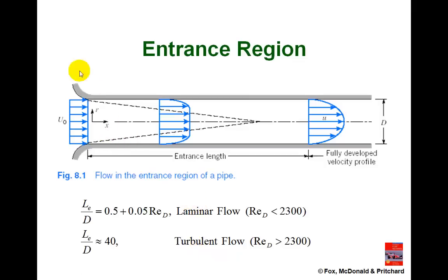If flow starts up from a reservoir over here on the left side and enters a pipe, especially with a smooth entrance as shown here, the flow is characterized by an almost blunt profile at a constant velocity. This is a flow that has inviscid characteristics, so at first you could consider neglecting the effects of viscosity in this flow. But what happens quickly as we move downstream is that we have the effects of the wall of the pipe, and viscosity tends to slow the flow down near the wall, and that's happening outside of this dotted line over here on either side.